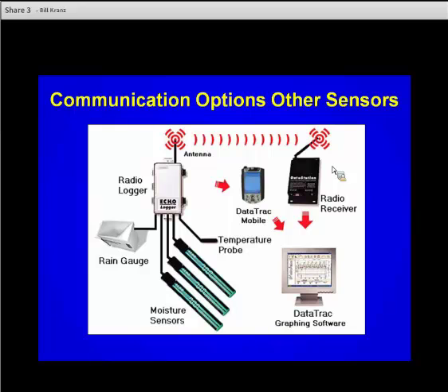As we go along, there are telemetry things coming online that allow people to record soil water sensors out in the field and access them from some distance away. It depends on the type of sensor you have as to how this might work. We do have a bit of an issue on center pivot irrigated fields in that we want the radio antenna and the transmitter to be above the crop canopy.